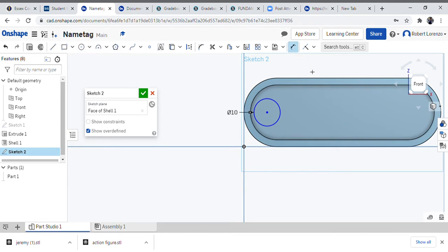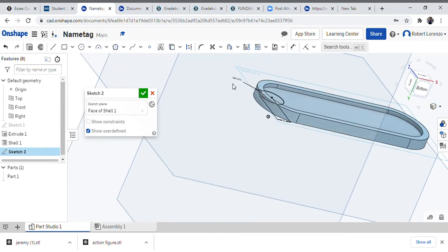We're dimensioning that line. Hold on, let me move this first. So a 45-degree angle represents a circle. So we're going to come in and dimension this. Find this point. Click, click. Drag our mouse down. Type 6. Enter. So here again we have a flat circle. Let me stop there. Press escape so I get out of the dimension tool. We have a flat circle that's really not going to do a whole lot for us.